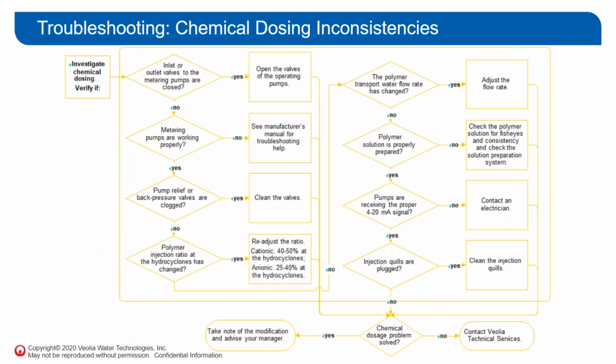And only one point for the chemical dosage inconsistency, that I just see so often, especially with the coagulants that have not necessarily impurities, but just a heavier makeup to them. They gum up the underside of the pressure relief valves or your back pressure valves, and these can make an uneven space, and it's easy for the reagent to pass back into the day tank.